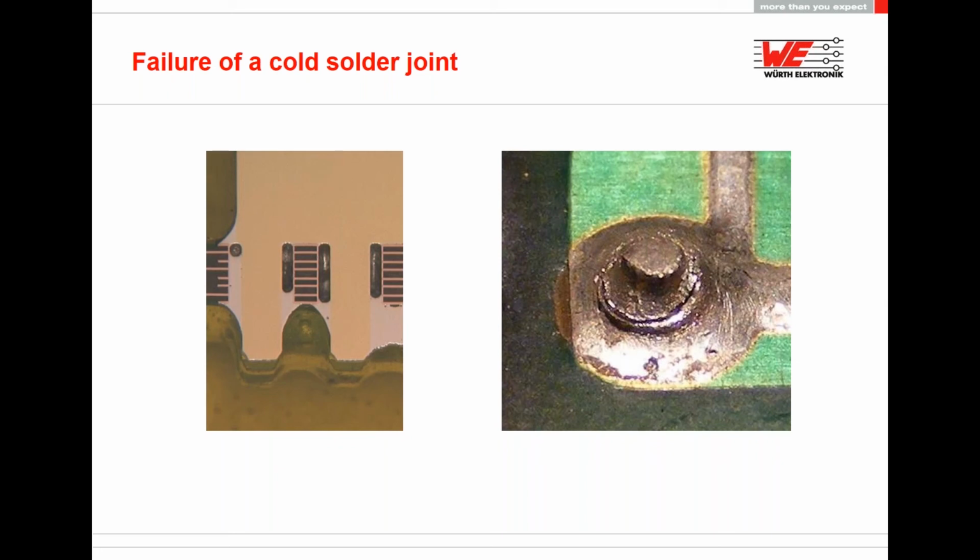Yeah, it's difficult. First of all, you need to know the ambient temperature. You need to know all the cross sections of the components. Then you need to know the delta T, so the allowed increase of temperature that you allow in your application. And it's not that easy to calculate because there are many parameters. You also have different parts on the PCB close to your other components.